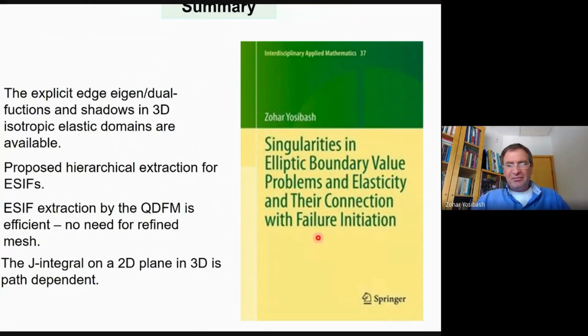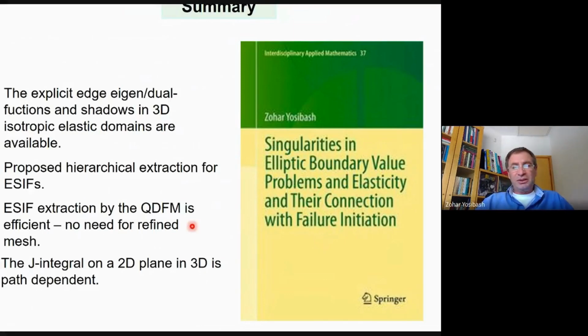So I come to an end. Most of the things that I have been discussing are described in this book, which came out in 2012, and I already found quite a number of typos, and I will have to correct them. But what I would like to say is that we can provide an explicit representation of the displacement and stress field in the vicinity of an edge. We can propose a hierarchical extraction for the edge stress intensity functions. It is very efficient, and we don't really need a refined mesh in the vicinity of this edge.